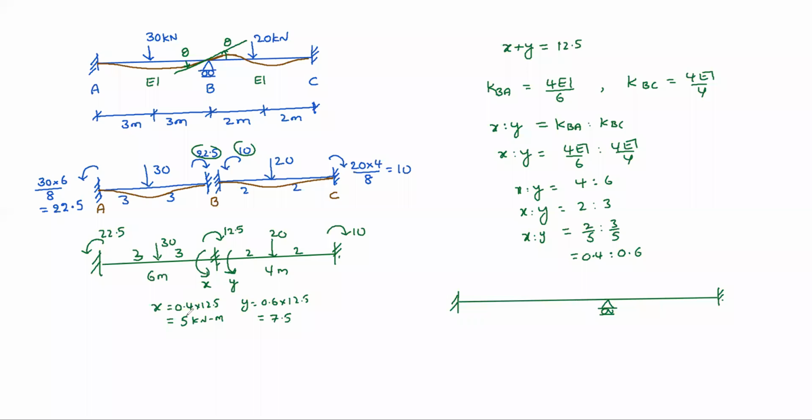See, by applying x moment 5 here, the carryover will come here. How much? 2.5. Here by applying 7.5 anti-clockwise, will come here 3.75 anti-clockwise. Now you can see 5, 7.5, 12.5 anti-clockwise and 12.5 clockwise. Net external couple is not there here now. It becomes 0. So now moments will become like this.